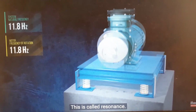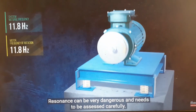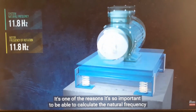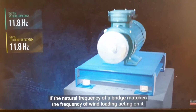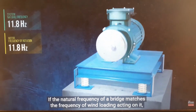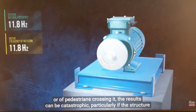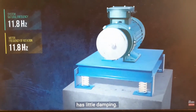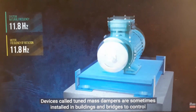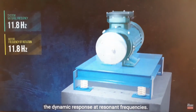This is called resonance. Resonance can be very dangerous and needs to be assessed carefully. It's one of the reasons it's so important to be able to calculate the natural frequency of a system. If the natural frequency of a bridge matches the frequency of wind loading acting on it, or of pedestrians crossing it, the results can be catastrophic, particularly if the structure has little damping. Devices called tuned mass dampers are sometimes installed in buildings and bridges to control the dynamic response at resonant frequencies.